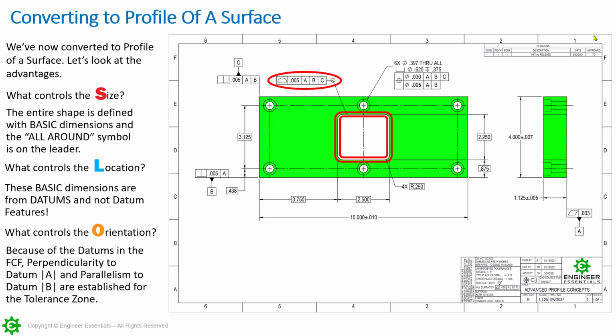Well, if we move over to the right side over here, we see datum feature symbol A over here. We know that this is the datum feature, and we know that the datum will become tangent to that, which for us, the datum simulator, will say is going to be a granite table. But whatever it's going to be, the simulator doesn't matter.